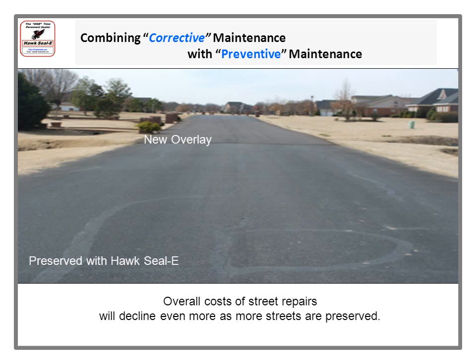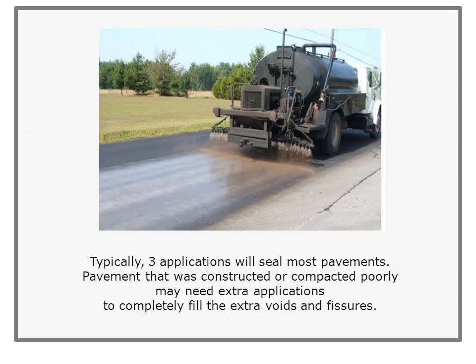The overall cost of street repairs will decline even as more and more streets are preserved. Typically, 3 applications will seal most pavements. Pavements that are constructed poorly or compacted poorly may need extra applications to completely fill the extra voids and fissures.